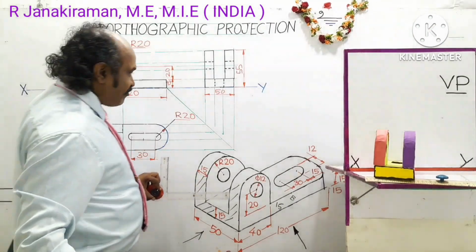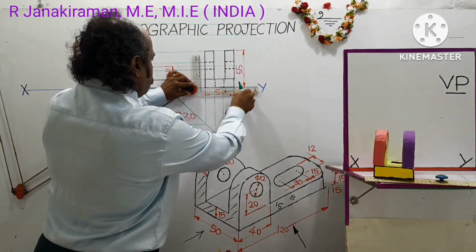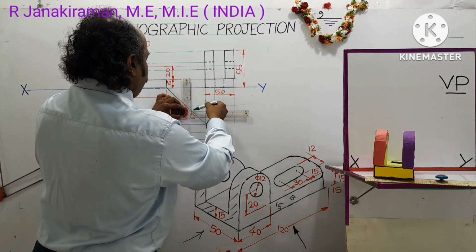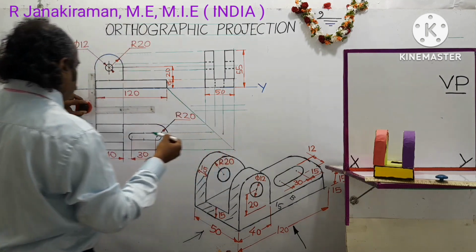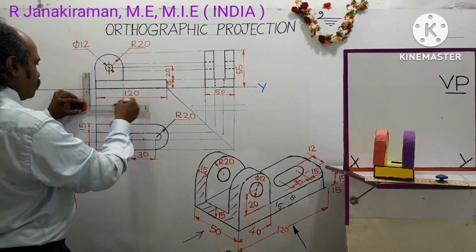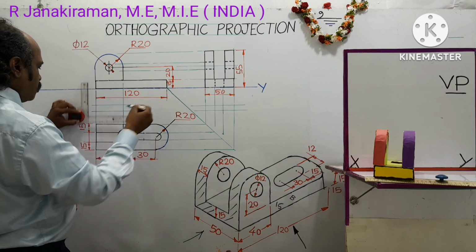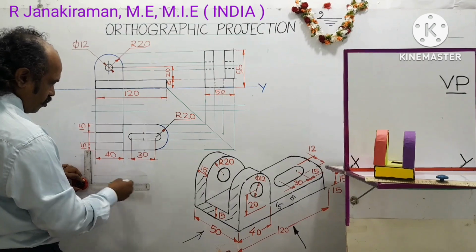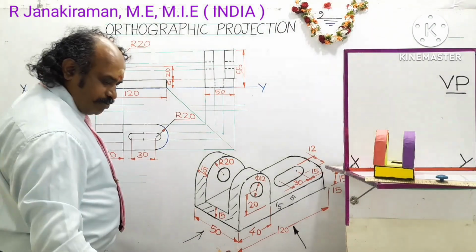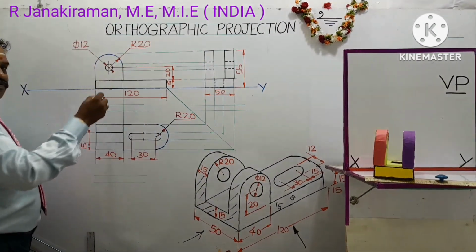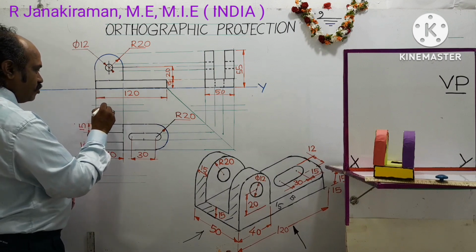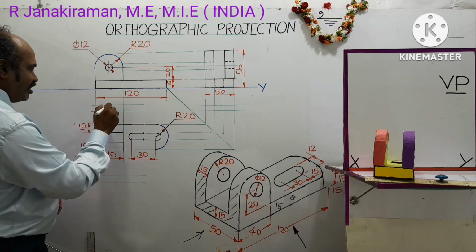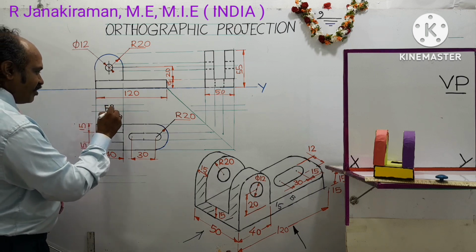So now I write the name of the diagram. Draw guidelines for uniform height of letters. Use an HB pencil for the writing work. This view is called the front view or elevation. We have already drawn two parallel lines for uniform height of letters using a 2H pencil. It is called the front view.